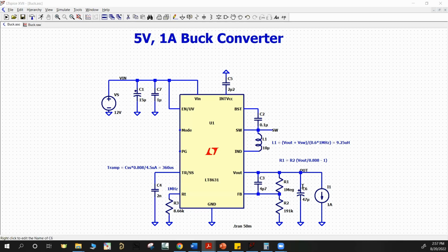So you guys recall I said that the larger the output capacitor is, the larger the amplitude of inrush current. But if we use a soft start feature, it ensures that the switch doesn't turn on as fast. It just introduces a little bit of extra delay time for how fast the switch gets fully turned on. It introduces that ramp up, which helps with the inrush, because now you're dampening how fast the rising edge of this inrush current can be.